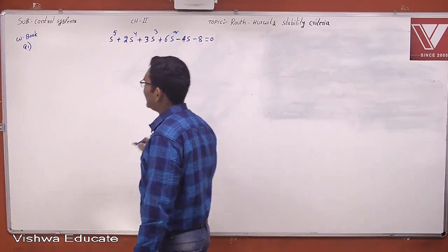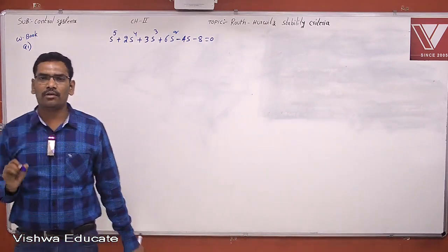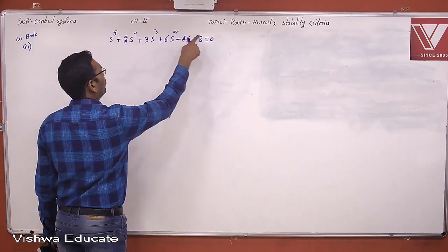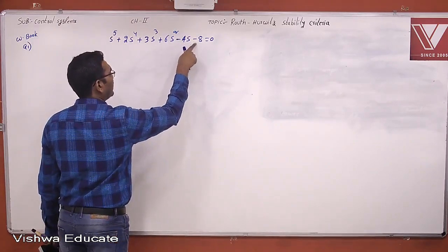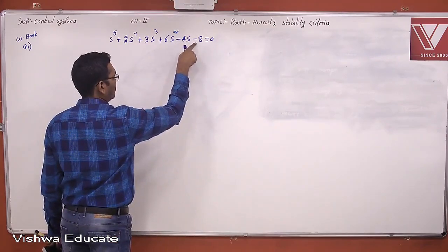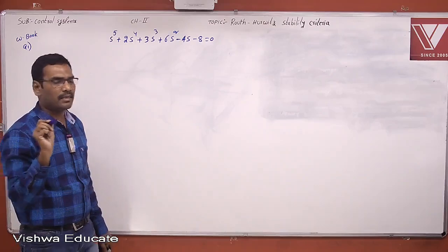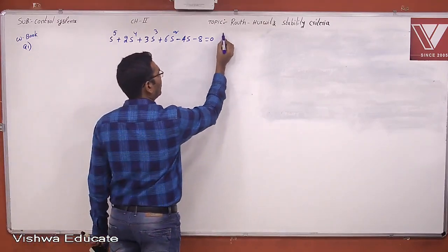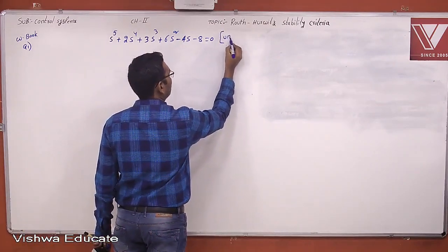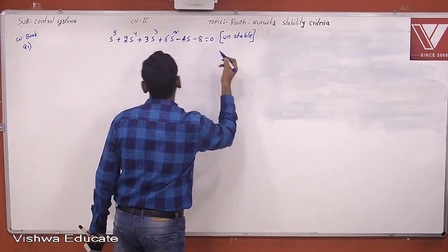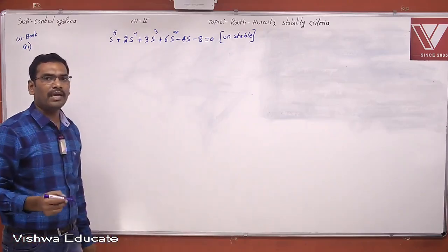While looking at this characteristic equation, without a second thought you can say the answer. 5, 4, 3, 2, 1, 0, no missing term, but there are negative terms, negative coefficients in the characteristic equation. System is 100% unstable, without doing anything. Because a negative term or missing term will lead to system instability beyond order 3.